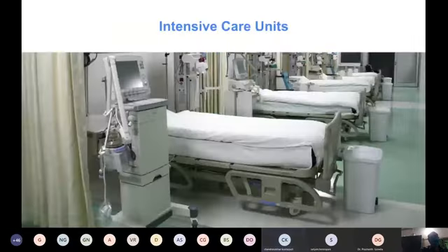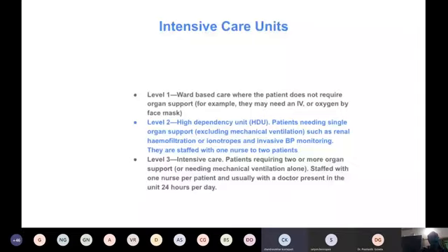ICUs, again, as all the veterans in the industry know, there are level 1, level 2 and level 3 ICUs. All the ICUs with different levels have different zoning and scavenging systems of air. Level 1 can be considered as semi-sterile, with a hygiene class.